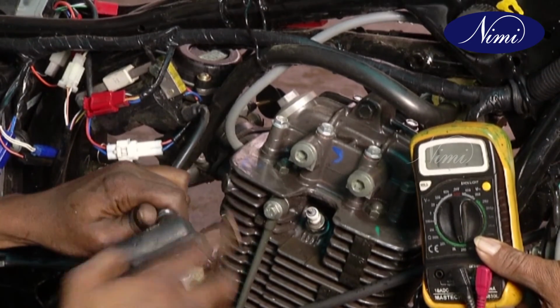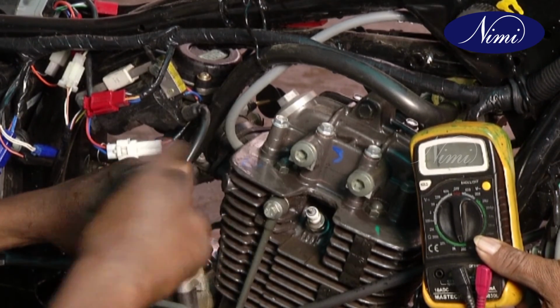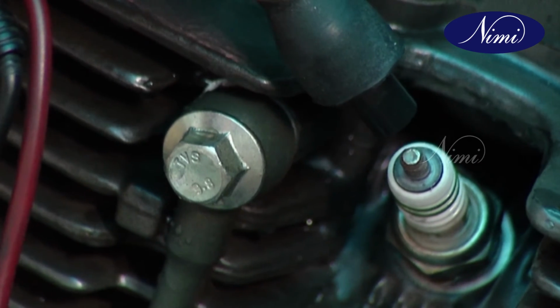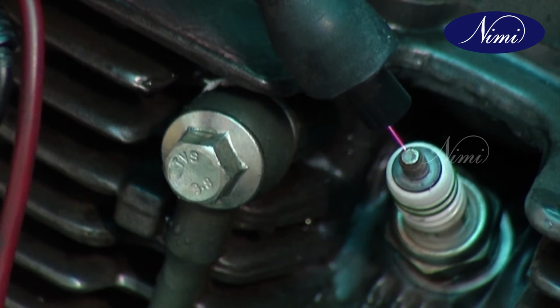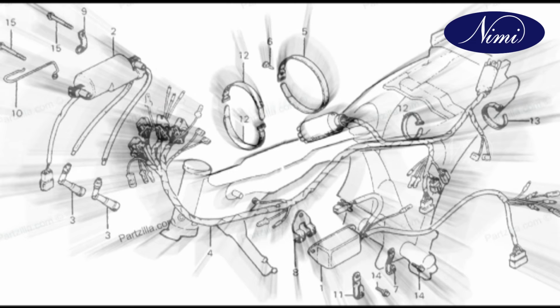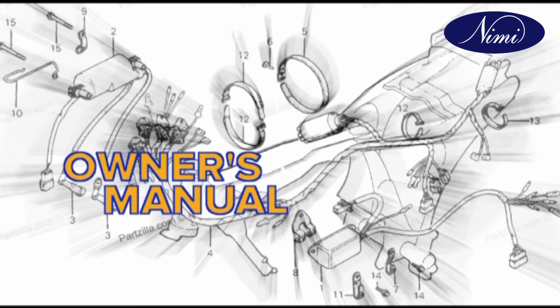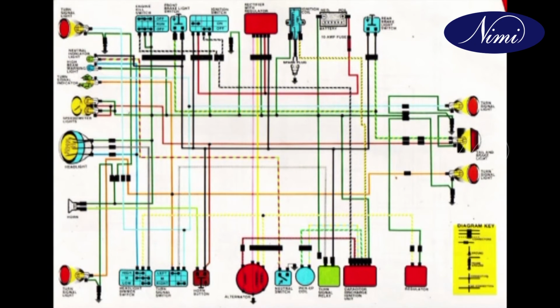Check the spark plug by conducting a spark test. It may also be tested in a spark plug testing machine. Owner's manual or service manual of any two-wheeler will contain the detailed wiring circuit diagram. Refer to the diagram and carry out the electrical checks.